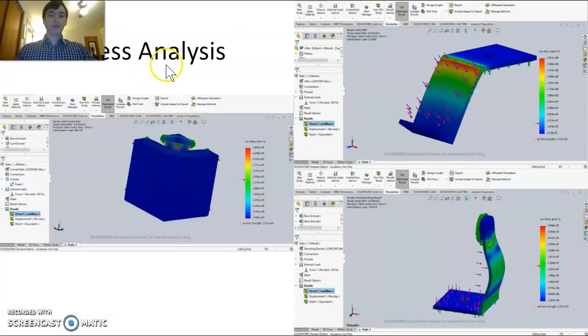The stress analysis was done to determine the effects of greater than usual forces on these pieces. I was looking for von Mises stresses, and as you can see in this figure on the left-hand side, it was built well, but the stresses deformed the inner part of it. However, that will not really be experienced in actuality, as it would be as if you were pushing the light